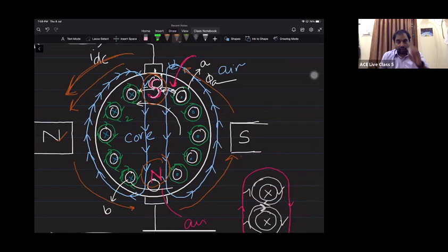So can I say as of now, in case of a DC motor, what is the reason that the armature will turn? The armature will twist, I'll give the statement. Whenever you start giving the excitation to the armature winding, the armature windings and armature winding currents form poles in the armature core.